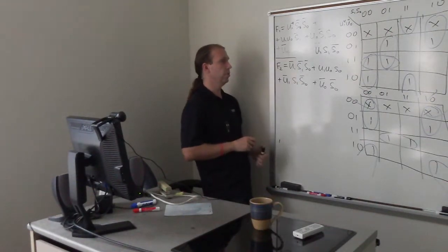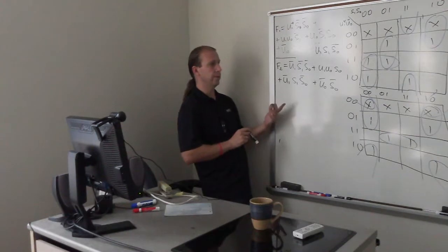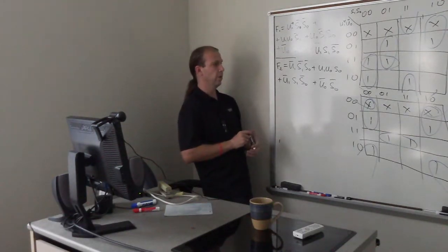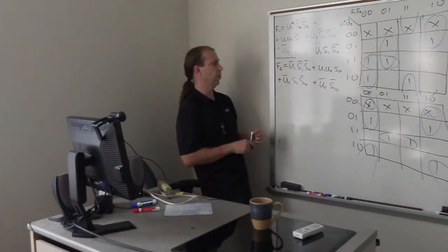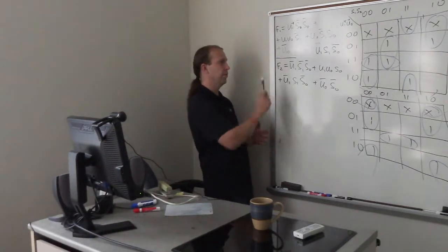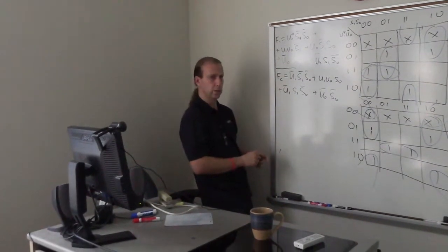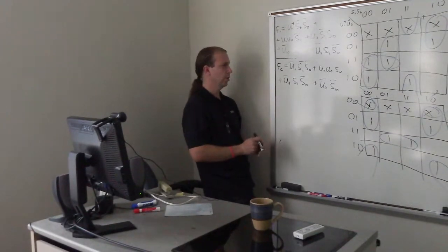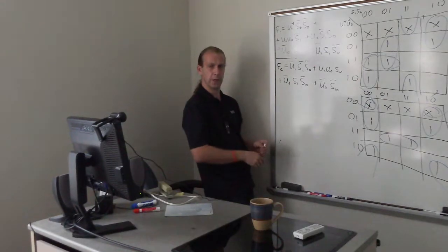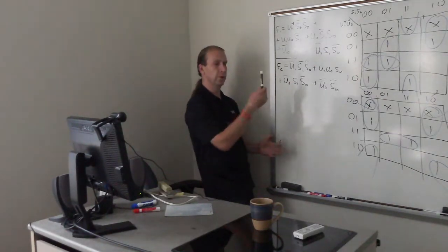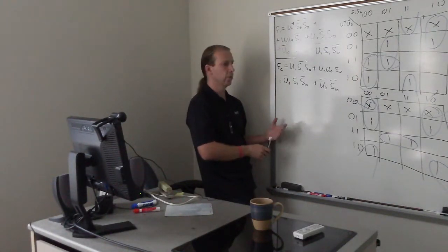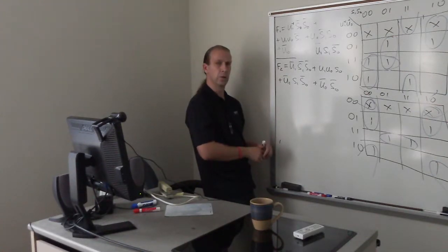So these are the 2 logical expressions, and you can see previously we had 8 terms from the truth table, but we ended up after optimization with 5 and 4 terms only. And terms are shorter and number of terms is less. That's how we use don't care conditions. And don't care conditions come from the fact of utilizing no operation input command.